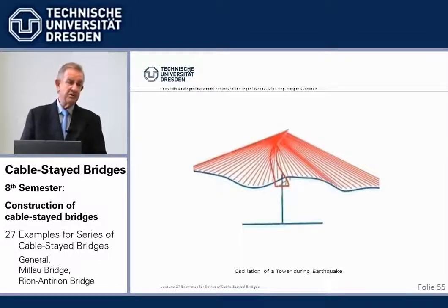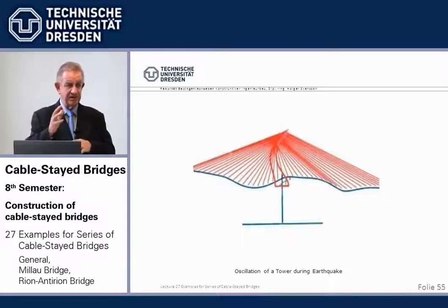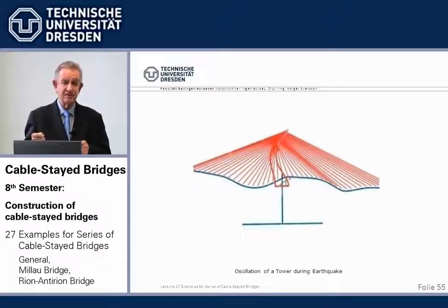Naturally, we have to look into the swinging tower. And that thing, depending on what frequency and accelerations we apply, oscillates in all directions and then has tension somewhere, which means cracked state, which means less stiffness, which influences the eigenfrequency and the moments under a given deformation and all that.